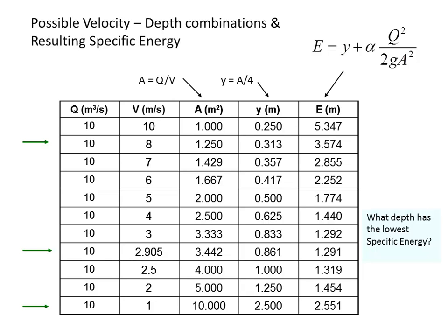And so what you can look at in this energy column is you think about that there's this one extreme where the energy is coming from a really high velocity, and the other extreme where the majority of the energy is coming from a deep depth. And what you'll notice is that there are places, 2.55 is our energy here.